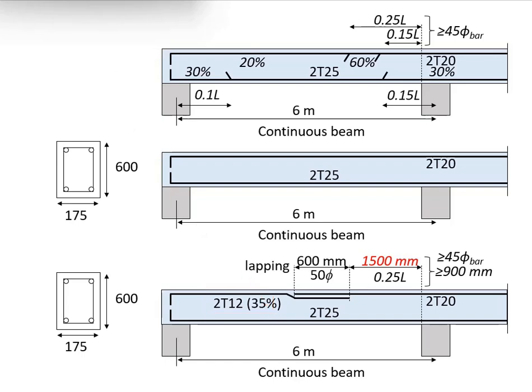And then what is the purpose of doing this lapping? While lapping the reinforcement bar, the longer the lapping length, the greater the bond with the concrete. The bond stress will accumulate along the length until the full lapping length is achieved.